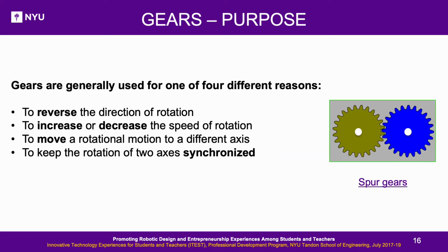Purpose of gears. Gears are generally used for one of 4 different reasons: to reverse the direction of rotation, to increase or decrease the speed of rotation, to move a rotational motion to a different axis, to keep the rotation of 2 axes synchronized.